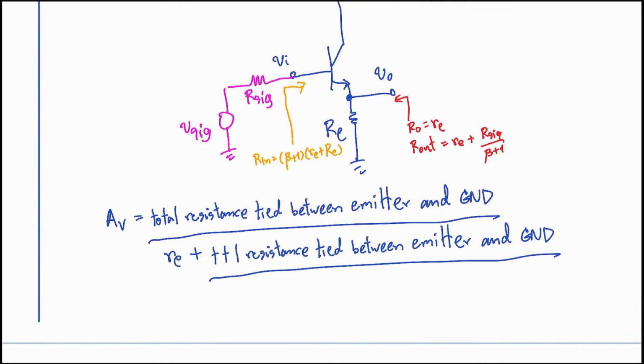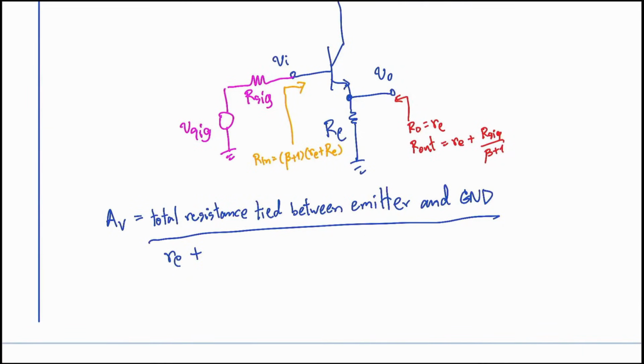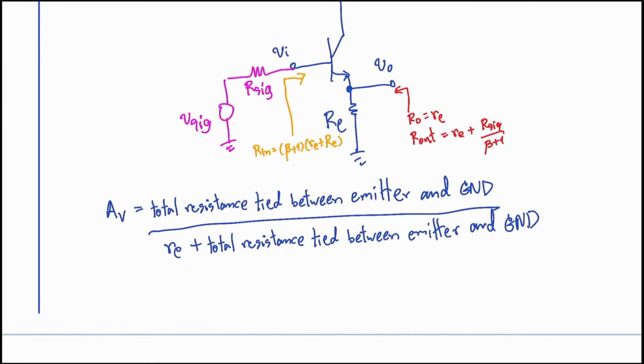Let me rephrase that to make it clearer. Essentially, the total value is calculated by taking the base resistance and adding the total resistance that exists specifically between the emitter terminal and the AC ground point. This is a really important step because that resistance path plays a major role in determining the overall gain and stability of the amplifier configuration we are analyzing.